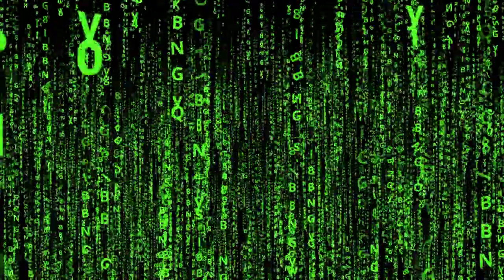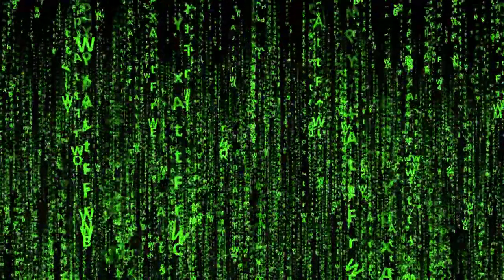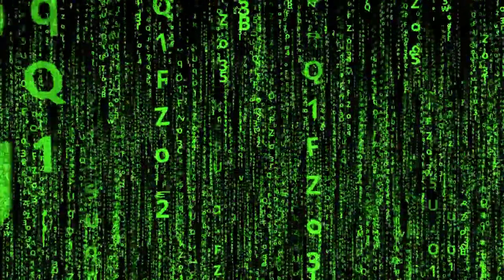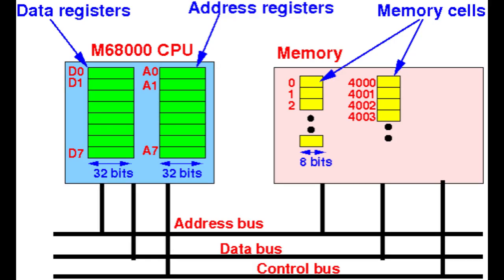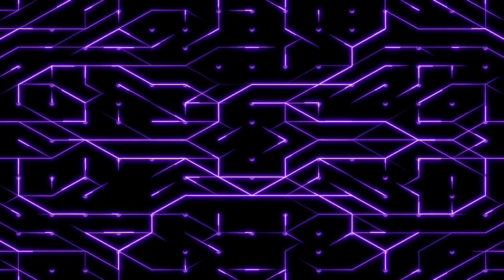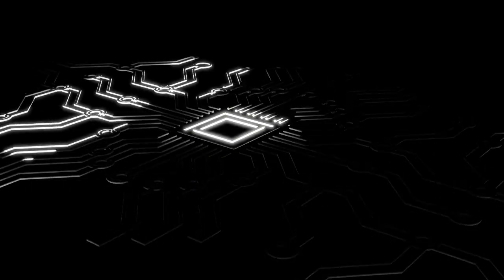Inside RAM are billions of tiny structures called memory cells. Each cell stores a single binary value, a 0 or a 1. Most modern RAM uses a technology called DRAM, which stores data using tiny capacitors that hold electrical charges. But those charges slowly leak away, which means the memory has to be constantly refreshed, usually thousands of times per second. RAM chips are manufactured using processes very similar to CPUs. They're mounted onto circuit boards to form the memory modules that plug directly into the motherboard.